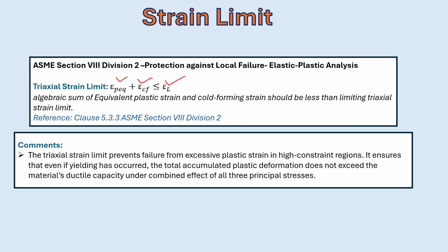The triaxial strain limit prevents failure from excessive plastic strain in high constraint regions. It ensures that even if yielding has occurred, the total accumulated plastic deformation does not exceed the material's ductile capacity under the combined effect of all three principal stresses.